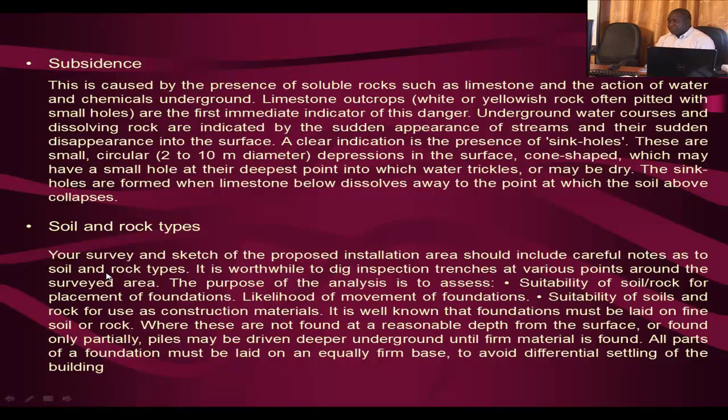The purpose of these trenches is to enable you to assess: 1. The suitability of the rock or soil for placement of foundations. The likelihood of movement of foundations can also be assessed. 2. Suitability of the soils and rock for use as construction materials.